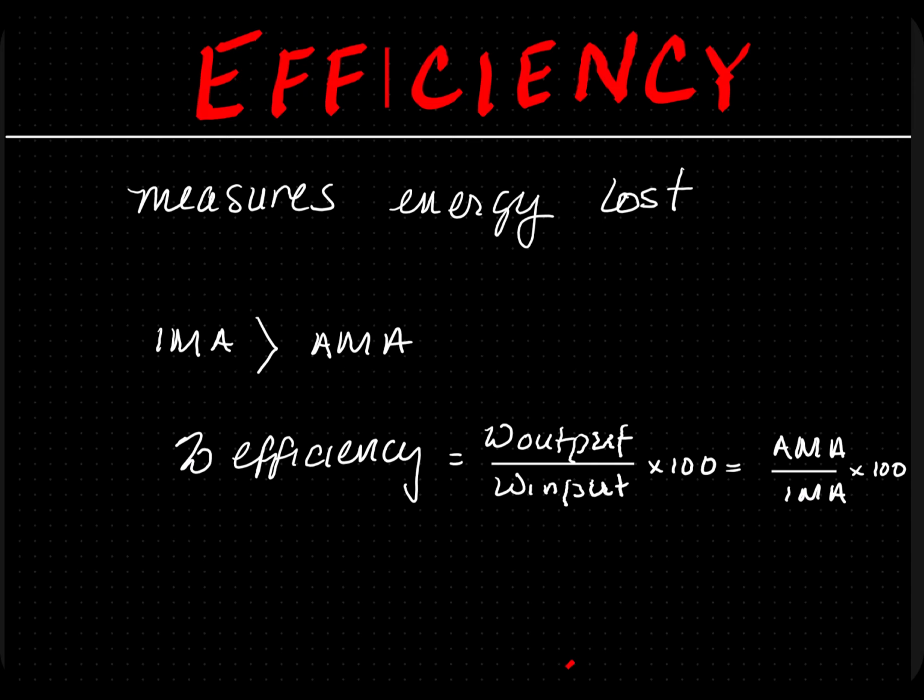For the 6 simple machines, the formulas are pretty much all the same. IMA is the ideal. It is always the distance of the effort divided by the distance of the resistance. You always measure and then calculate. You don't have to build anything. AMA, you must build and measure what actually happened. The formula is force of resistance divided by the effort force. All the formulas are the same for all 6 simple machines. However, for pulleys, you can also calculate IMA by the number of strands.